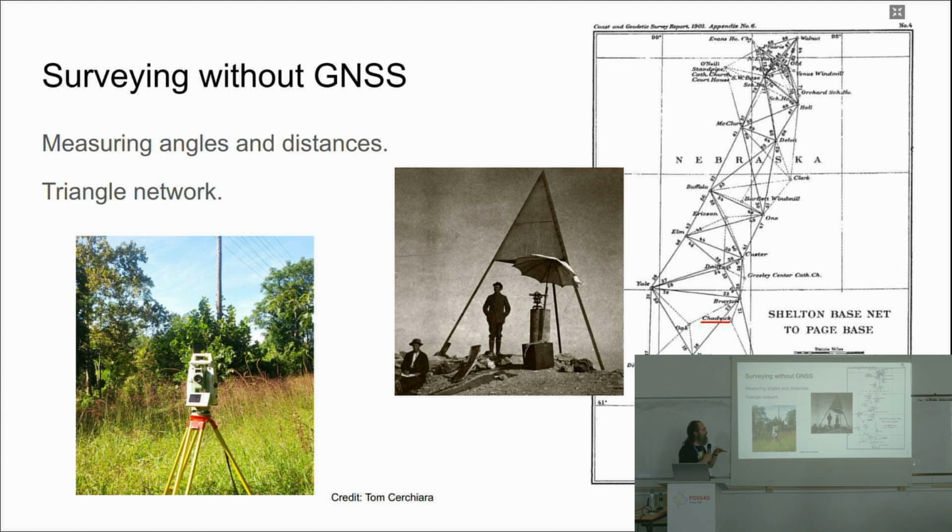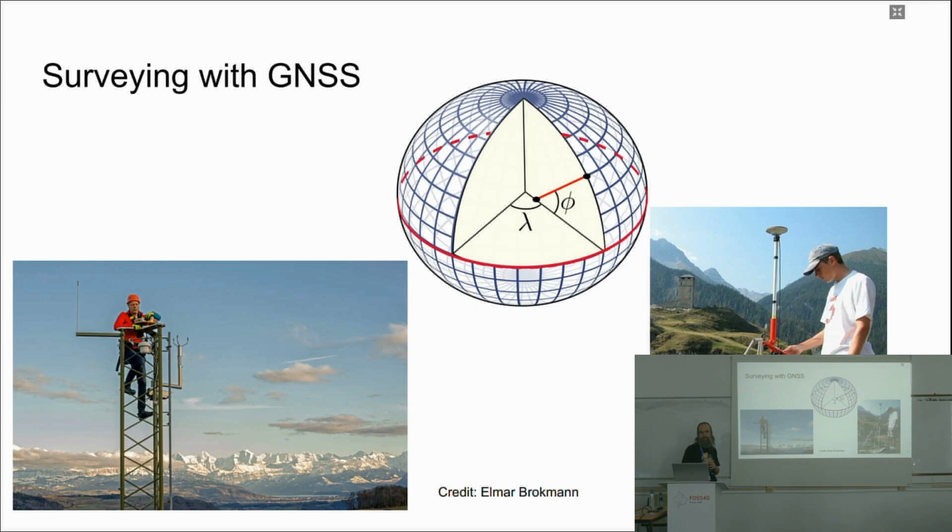That lets the surveyors and topographers make triangulations on the terrain. And with this triangulation, you can deduce later the coordinates of any point in the field or in the country. But nowadays, with these GNSS constellations, what we use is a GNSS receiver and making some maths to get the coordinate, an absolute coordinate, well, a georeferenced coordinate.